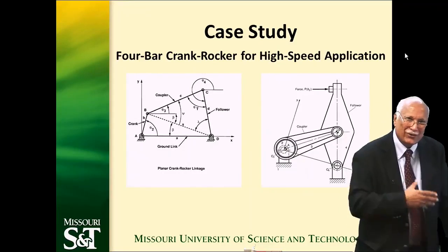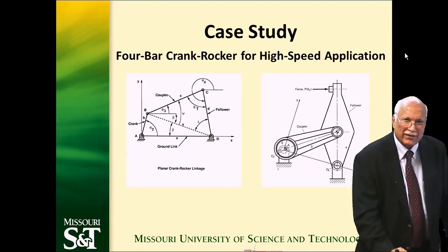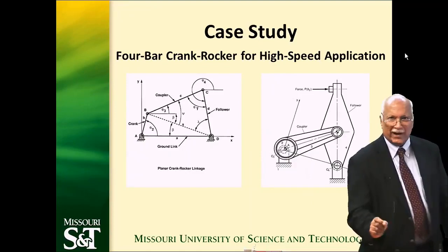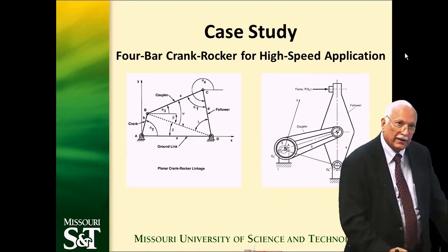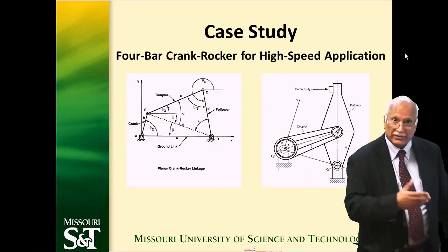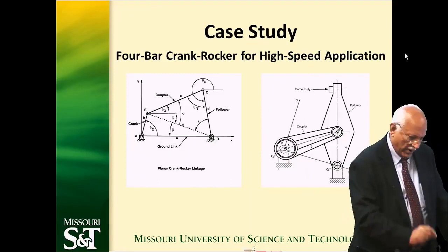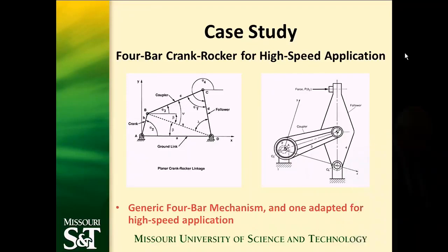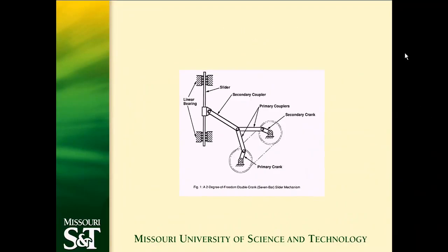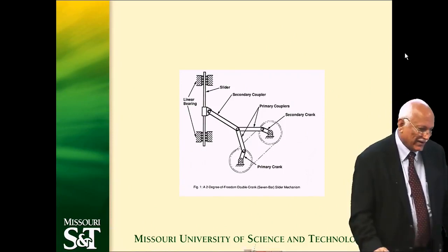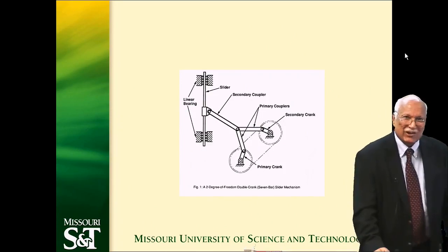So the whole thing will rely on the entire philosophy and the design of mechanisms using small cranks. And we'll look at analytical expressions that would help us synthesize these mechanisms for required needs. Here's a geared 5-bar based 7-bar slider mechanism.